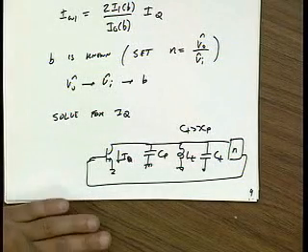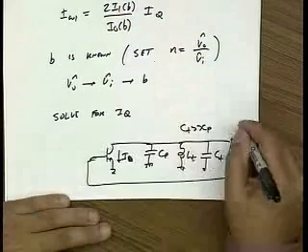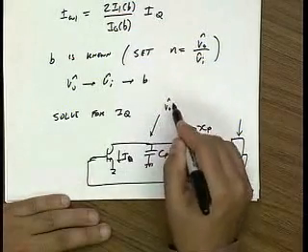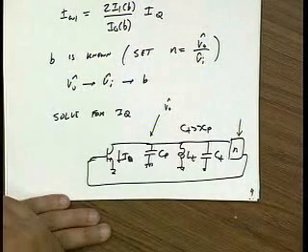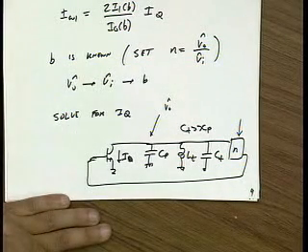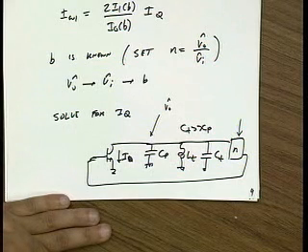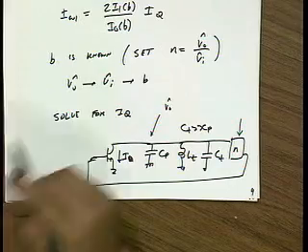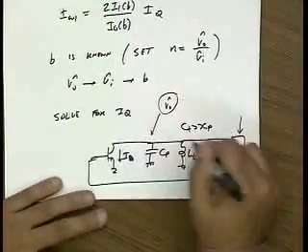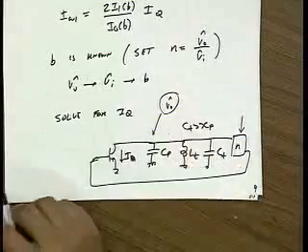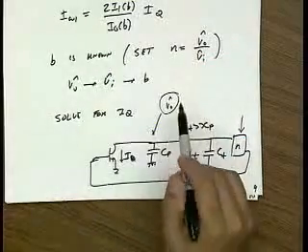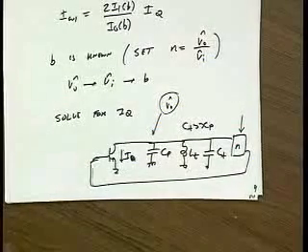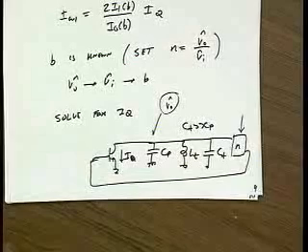Okay, and so you see there is some design freedom. We had the freedom to choose N. In some ways we also had the freedom to choose VO. In some situations we don't. We need full rail-to-rail or close to it to get the best performance. But for now, let's just focus on the free parameters. So because there are so many design variables, we outlined a procedure that if you fix VO and N, then everything is known. You can basically find all the components. Okay.